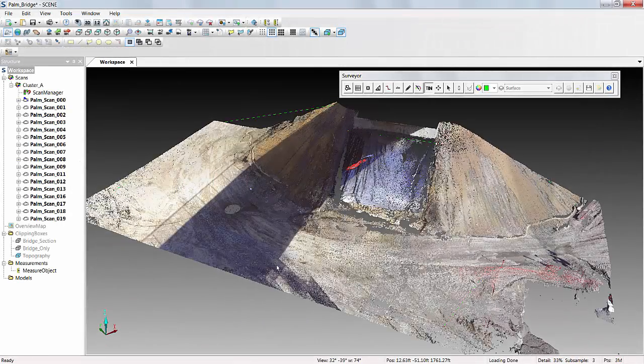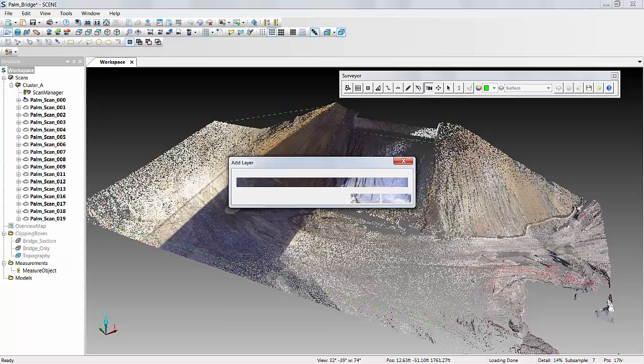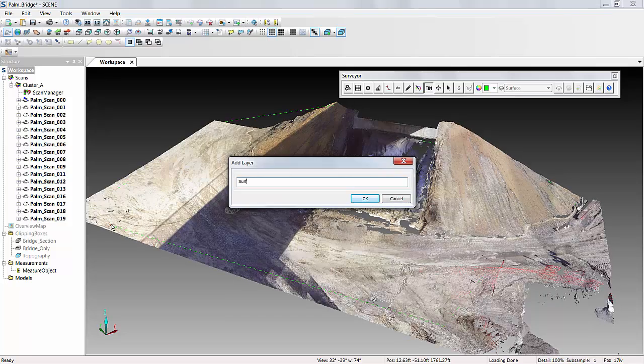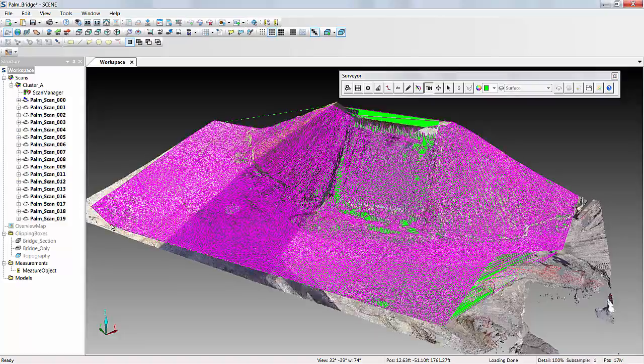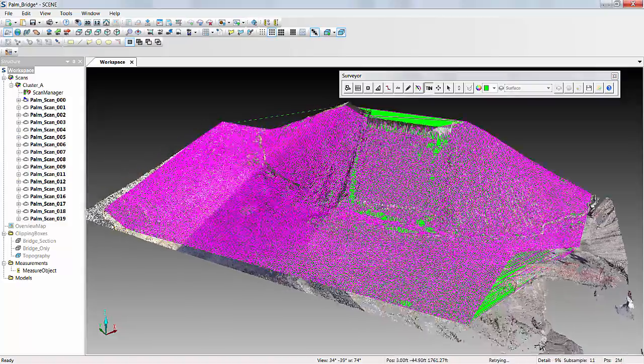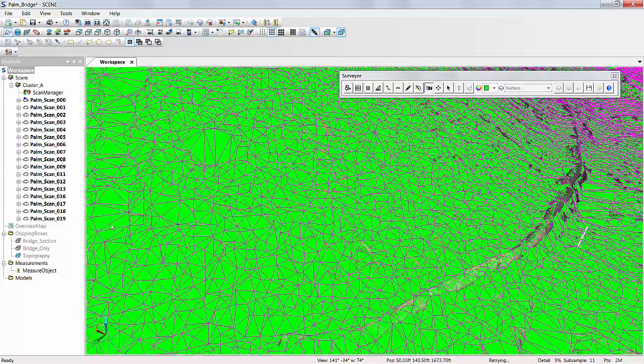Surfaces. So of course for our buttresses, we were able to just capture that along with the rest of the bridge that we happen to be capturing, and using the Builder or the Surveyor app can produce a TIN surface directly inside of Scene that we can then export to LandXML.